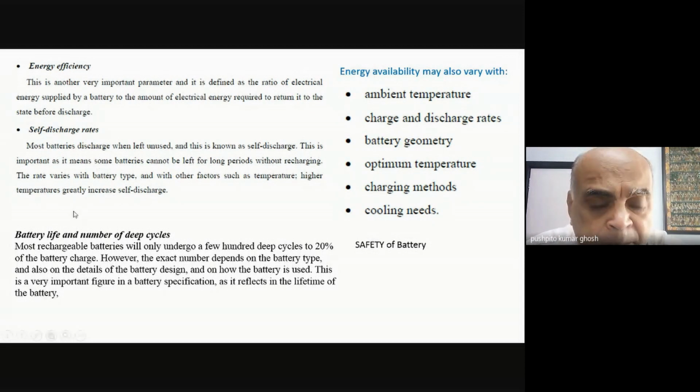Battery weak ho gaya. Remember another thing, that a battery's performance also depends on to what extent am I discharging or draining out my battery. Let's say I'm the careless type, and every day your mobile is going dead, and you say, oh, my mobile is gone. Now I have to again start from scratch, from zero charge. It has to be charged up. That's known as a deep cycle. The more number of deep cycles you have of charging and discharging, the more rapidly your battery will deteriorate. Ideally, you should make sure that you are recharging your battery when you have got at least 20-30% power left. That's what ideally you should do.